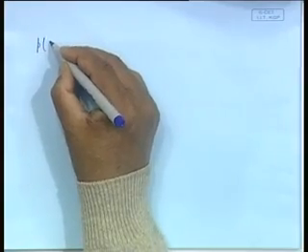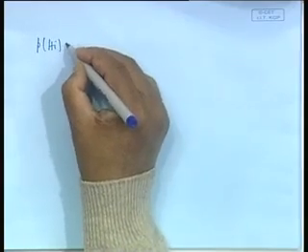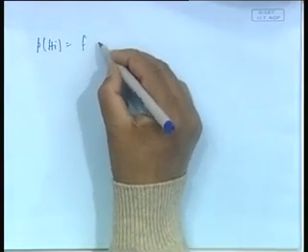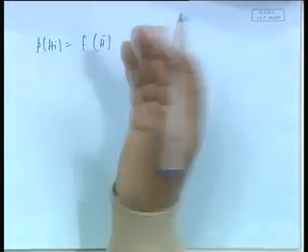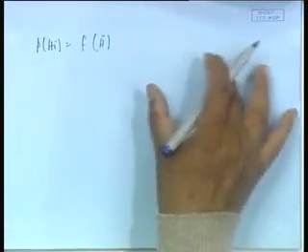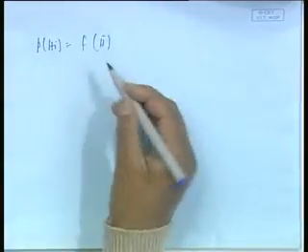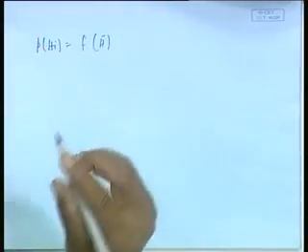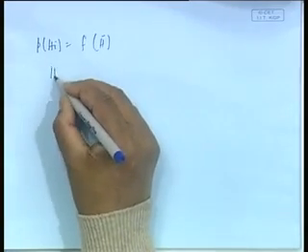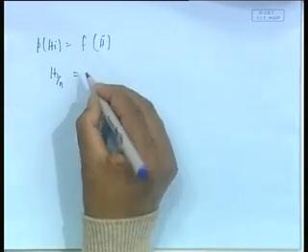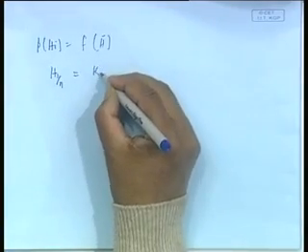Now the interesting point is that it turns out if I were to use a Rayleigh distribution, because in Rayleigh distribution I know this P of H as a function of H bar, basically that is what the expression is. So all quantities of H 1/n can be expressed as a constant into H bar.